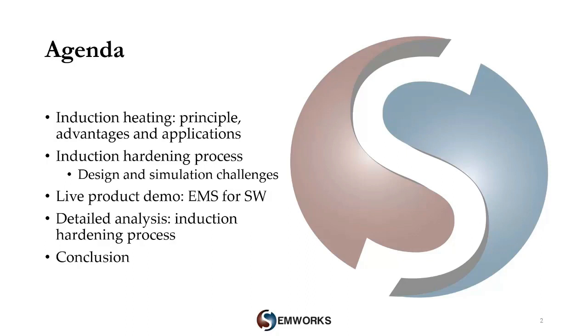Then we will move to a live demonstration of the EMS interface inside SolidWorks. Later on, using simulation, a detailed analysis of the induction hardening process of a spur gear will be done. We will study the impact of some processing factors on the gear temperature, and we will try to estimate the generated electromagnetic and thermal stresses. And finally, a conclusion.